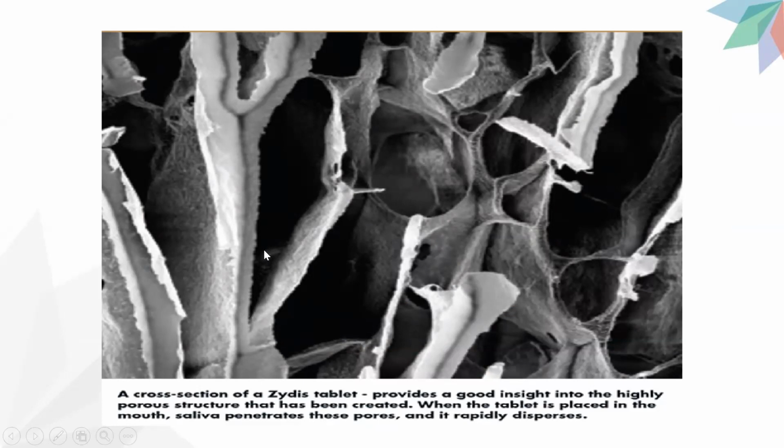Under a scanning electron microscope, in this figure, there is a cross-section of a Zydis tablet to provide a good insight into the highly porous structure. This porous structure is due to the sublimation process in freeze drying after removal of water. These pores enable the penetration of saliva inside the tablet so that the tablet rapidly disperses. This is the importance of freeze drying in the formation of